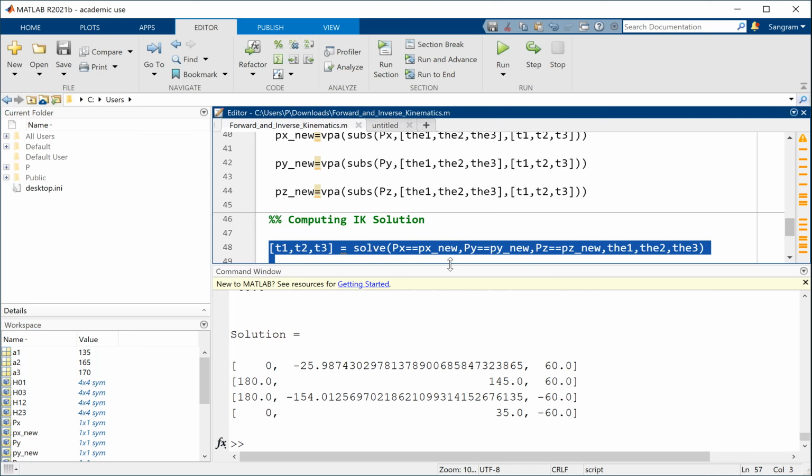For example, you can say that I don't want my joint angles to go beyond certain values. So that eliminates some solutions. Or my second solution should be close to the previous solution. That will eliminate some of those solutions. So basically, you can add some if-then type of statements to eliminate, out of these 4, 3 solutions, and then you get the answer.